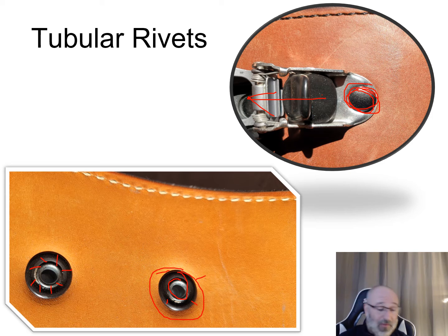And there are other types of rivets that we'll get into, some rapid rivets and double rivets that I looked at and just did not work for this application, didn't have the strength that I would need. And a lot of this, we do have some calculations that we'll get to later in this lecture on how we can calculate rivet strengths for your application. But also, as we've seen in this class, there are some unforeseen things that are hard to fit into our analytical solutions that we actually just need to go out there and do some testing.